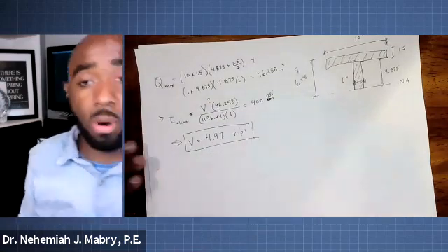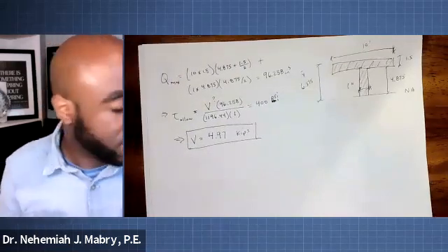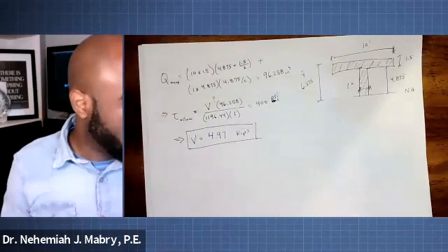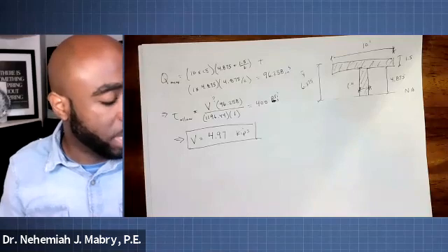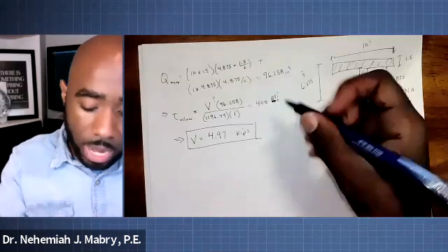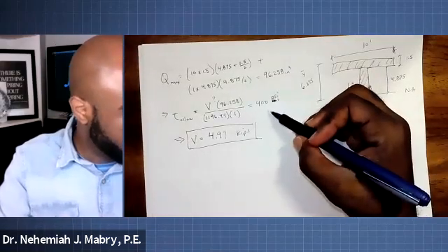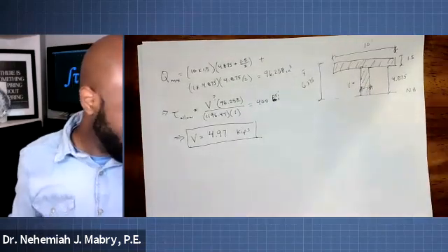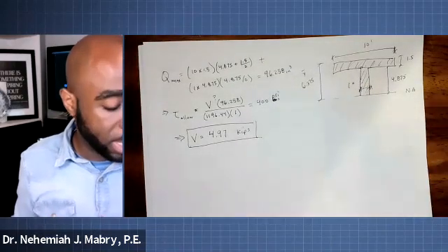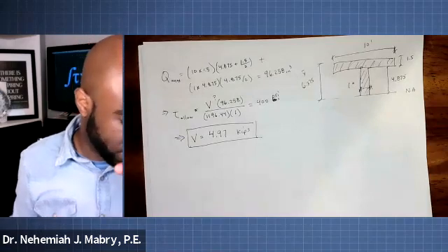That solves the first part of the problem, which was to find or determine the maximum shear V it can support if it had an allowable stress of 400 PSI. Now we have to find the maximum spacing. That's what we have to do next, find the maximum spacing.